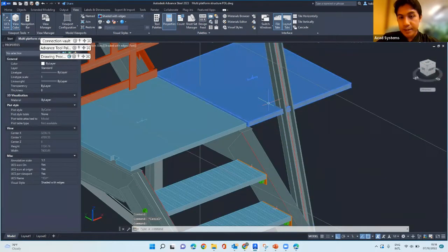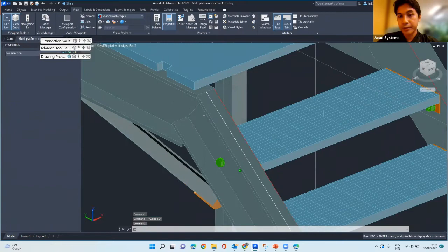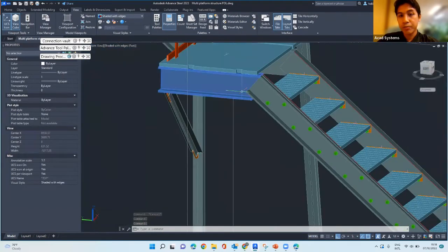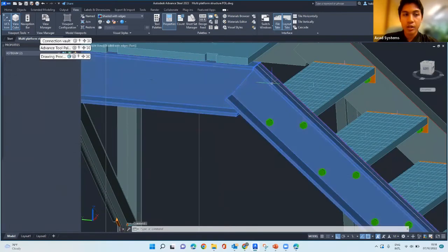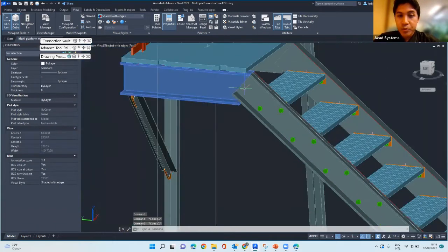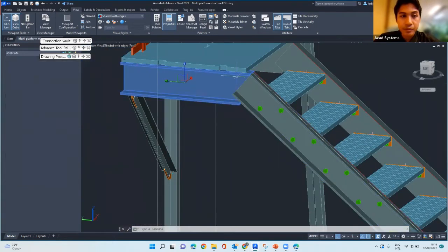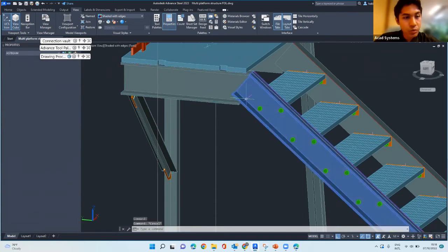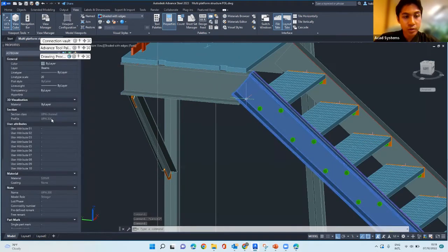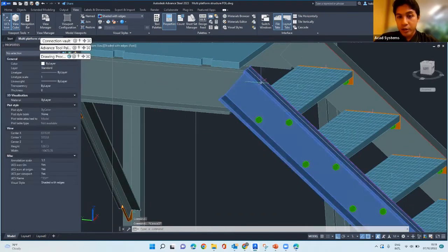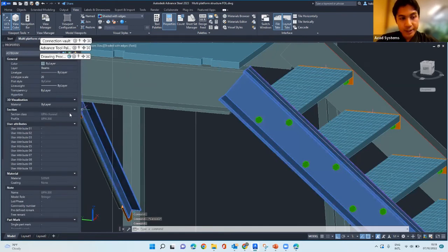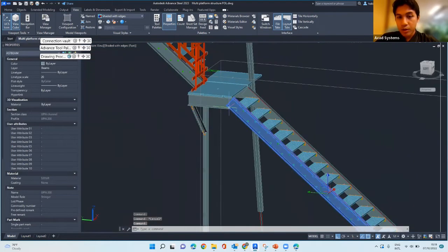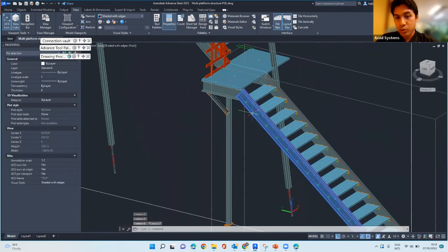So now we have moved it in place, and I want to settle this part. I have to make a proper joint between this beam and this beam. For this, I will first have to match the beam size. If I click here and look at the section properties, it's using profile UPN 220, and this one is profile UPN 200. That 200 is most likely the height of the profile, and they should match each other. So how do I change this beam to 220?